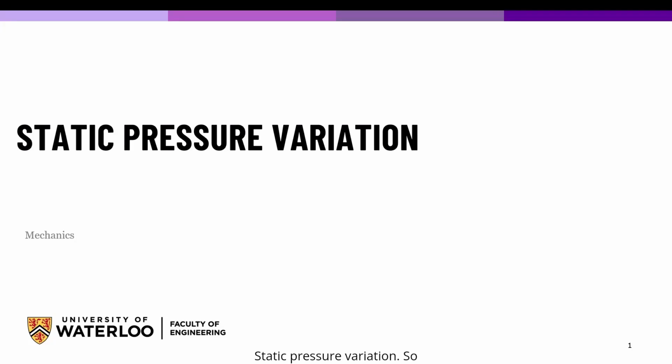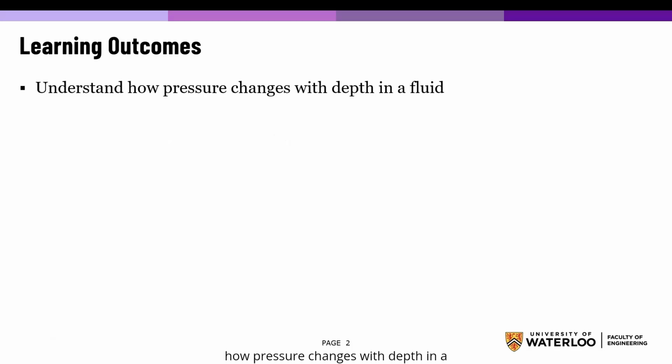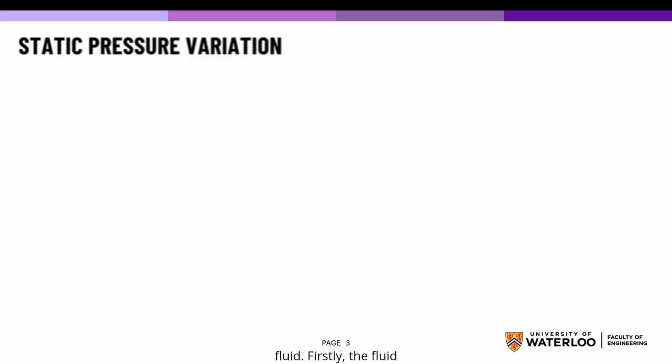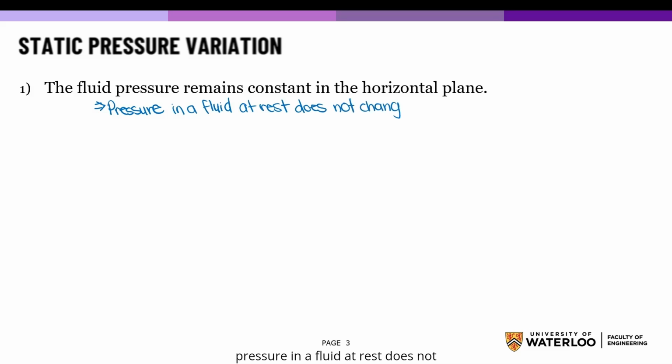Static pressure variation. So here is our learning outcome: understand how pressure changes with depth in a fluid. Firstly, the fluid pressure remains constant in the horizontal plane. This means that the pressure in a fluid at rest does not change in the horizontal direction. Second, the fluid pressure increases linearly with depth.